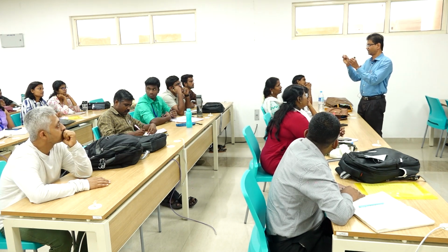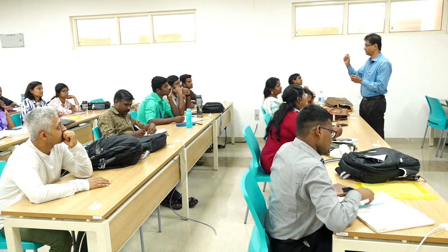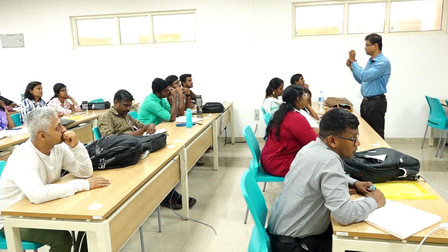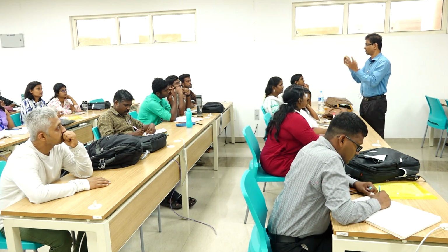No. This is a big donor; if this is the donor phase, this is the acceptor phase. If you want the exciton to separate out, the domain size should be within 20-30 nanometer, which is the exciton diffusion length. You diffuse 30 nanometer, and when you reach the heterojunction, it gets separated out. In this case, it's around 500 nanometer, very much larger than the exciton diffusion length. So the exciton is not dissociated; it recombines. We are not getting enough charge separation, and that's why the current is very, very low here.